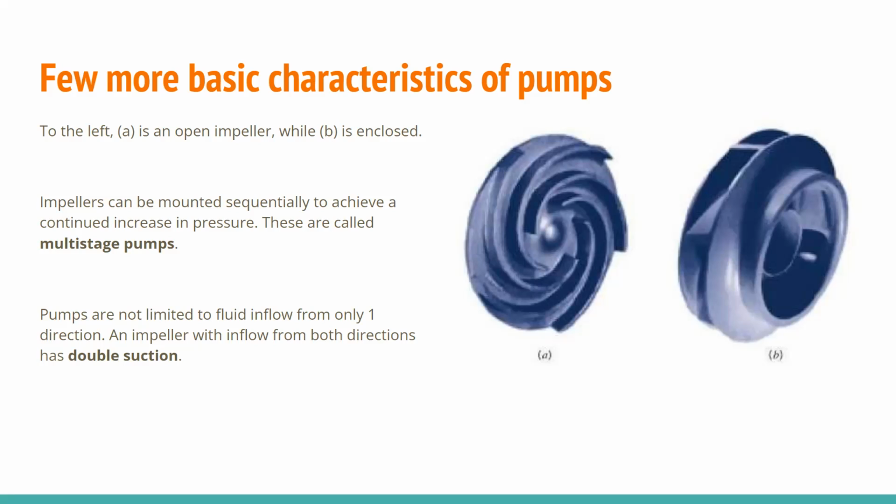They're also not limited to fluid inflow from only one direction. An impeller with inflow from both directions, at the eye, is a double suction impeller, and hence a double suction pump.